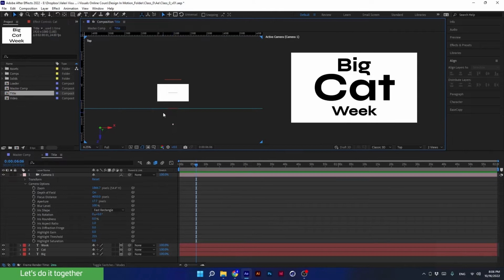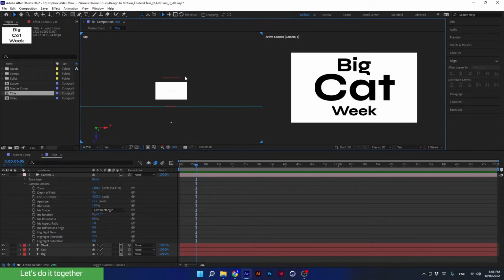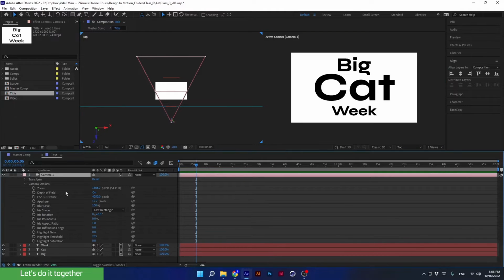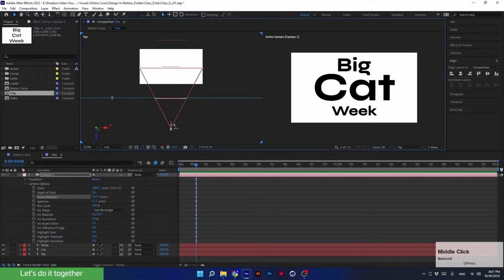We don't have to use guides. I'm just showing that there is such a possibility. Okay, so after we know where the area we want to focus is, you can press Ctrl-R to close the rollers. And now, let's go to the focus distance parameter and change the values until we see that the distance line reaches the location we marked. So I'll drag the parameter when I press Shift, so that the values change in big jumps. And here, the focus distance is where I wanted, but I still don't see any change.